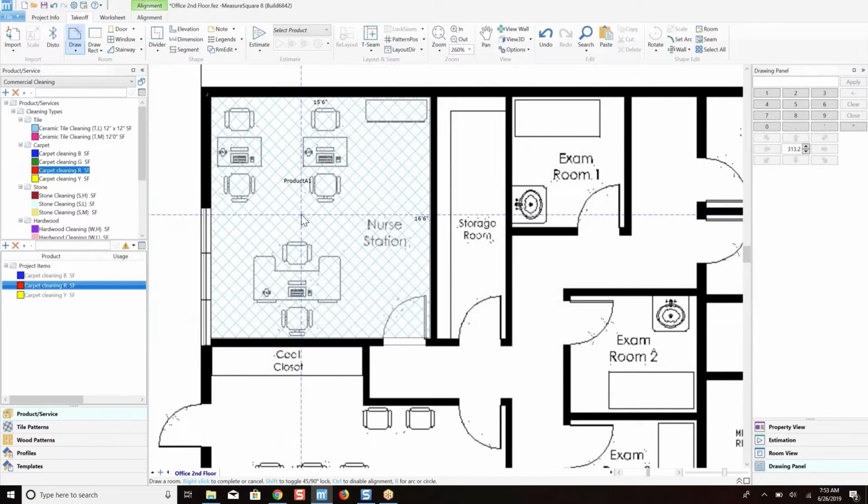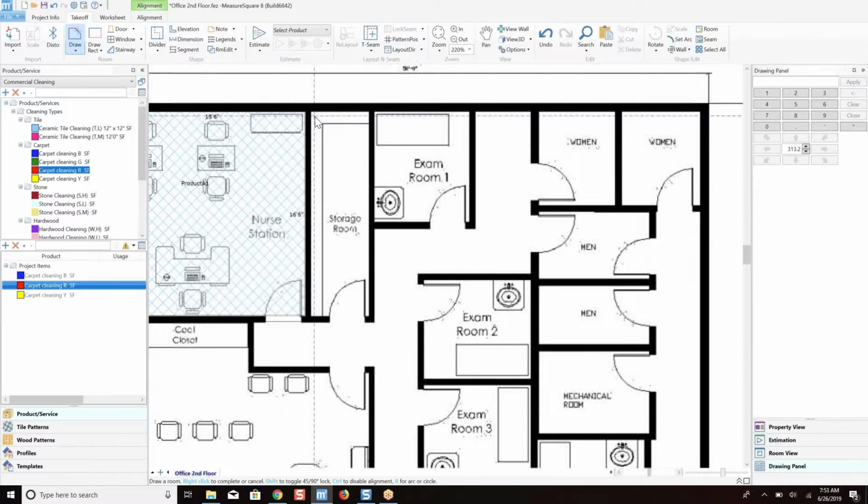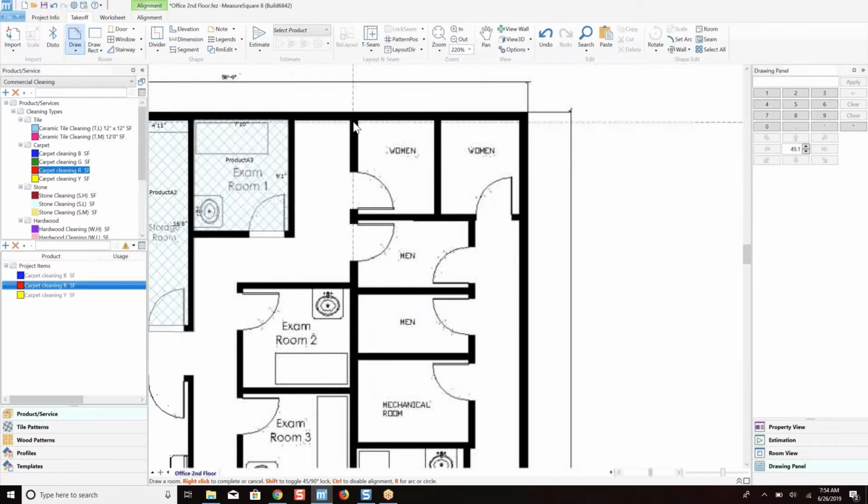I have a crosshatch turned on, as we call it, to show that I've traced the room, but nothing's been applied to it yet. So now I'll move on to the next one. And when you see those lines pop up, as I do right now, those little green highlights, I'm snapping to the room drawn next to it so that everything's lined up, and this will help us in auto-completing the hallway in this usage scenario. Again, I'm always just left-clicking on each corner and dragging to the opposite side. So I'm going to do all these basic shapes.